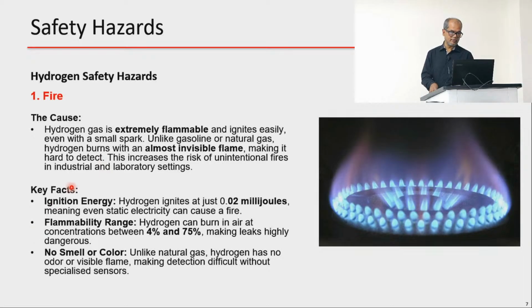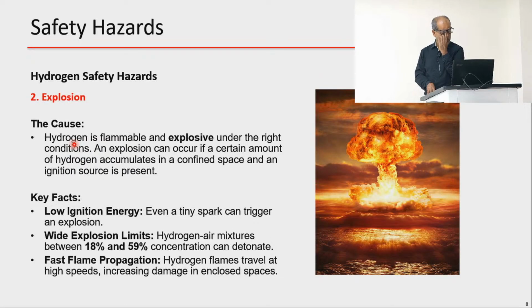And here are some of the facts. It ignites with, as I said, very small energy. It only needs 0.02 millijoules, so it's a fraction of a millijoule that can cause a fire. So you see what a small amount of energy can cause a fire. And flammability, we already mentioned, is 4% to 75%, making leaks highly dangerous. And the lack of smell and color also makes things more difficult.